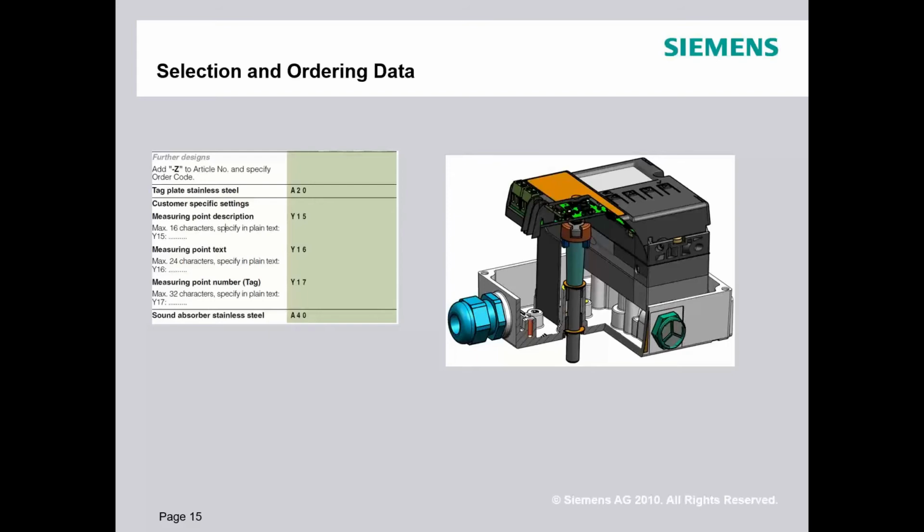Most of them are stainless, so that's not going to be an issue for you. All we need to know is, if it's a linear valve, let's just throw this one at Fisher: I've got a 657 size 40 with an inch stroke. That's all I need to know, and we'll get you the right kit.